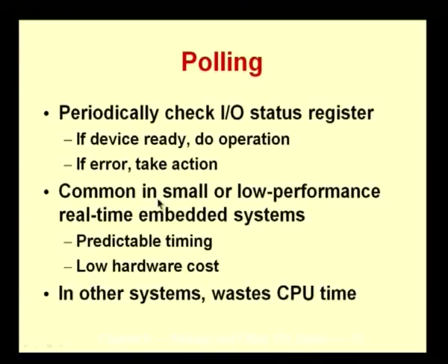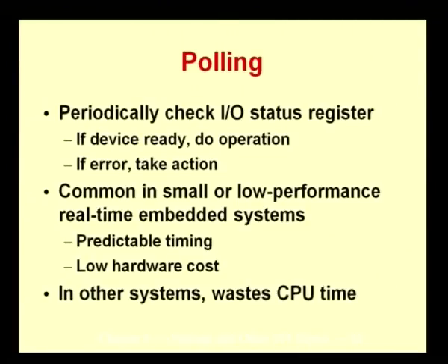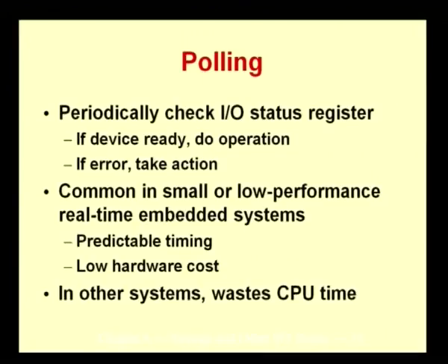This kind of polling mode is suitable for small or low performance real time embedded systems, that is, where you have a limited number of devices that you are polling. It can be used when you need predictable timing and the hardware cost is low, because you do not have any special hardware for interrupts or any such operations. So, the cost of the hardware can be maintained as low. But the only problem is that it will waste a lot of CPU time, because you have to execute instructions to come and check again and again. So, it is wasteful of the CPU time.